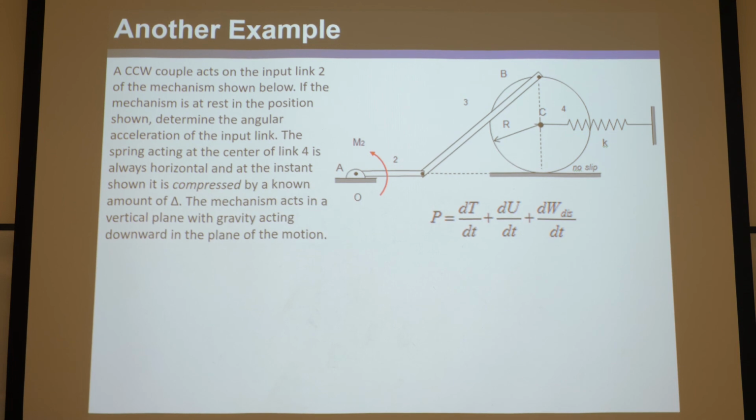Now, of course, if this really is a rack and pinion and it's got teeth, even though the joint is counted as a J1, 1 degree of freedom, it's rolling only because you don't shear off the teeth. As they go through their mesh, from points C to P, it's actually sliding. The teeth are sliding, and from P to D, they're also sliding. It's only at point P, the pitch point, that there's pure rolling. So in reality, you may actually have to take friction into account, even though it says there's no slip here, if this is a rack and pinion with teeth. But anyway, that's just harkening back to our last lecture. For now, we're going to say we don't have to take it into account.